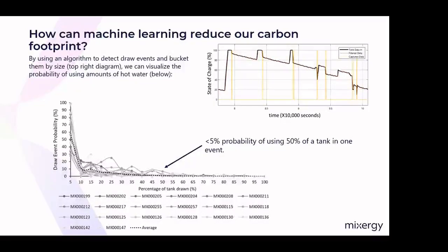we're sizing hot water on a one-in-a-million chance that the hot water could be overloaded, with everyone in the household taking water one after each other. We've got visitors. And what we're doing throughout the year is storing excess energy in water which isn't being used and is lost in standing losses.